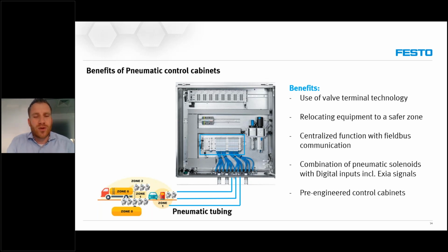So there's no need for additional remote I/O equipment or additional cabinets in the field. And one feature for Festo, what we are able to do with the control cabinets for explosive environments, is that we have pre-engineered a lot of multiple designs for the majority of the cases that are possible. So this also brings me to the next part when it comes to engineering a pneumatic control cabinet.